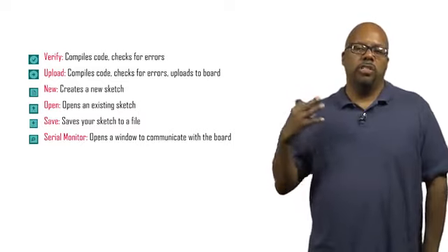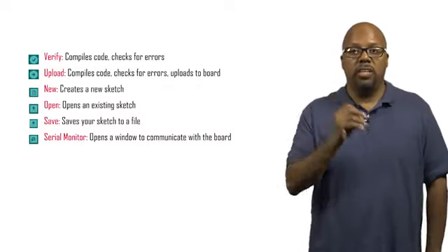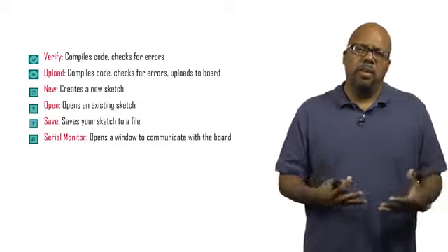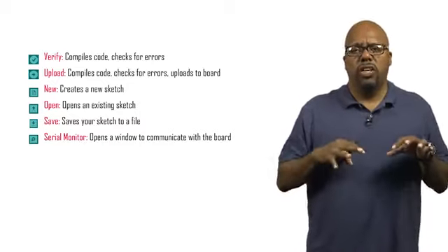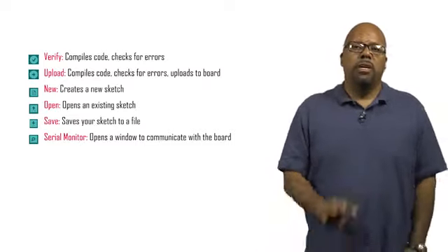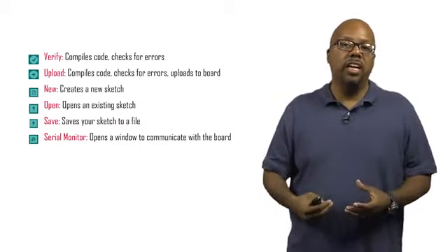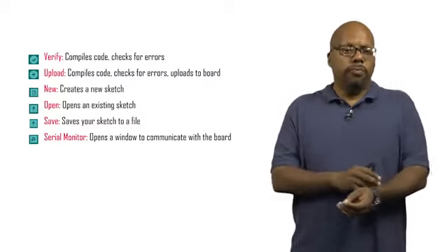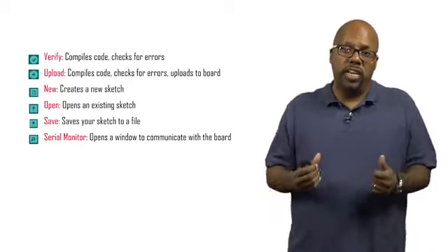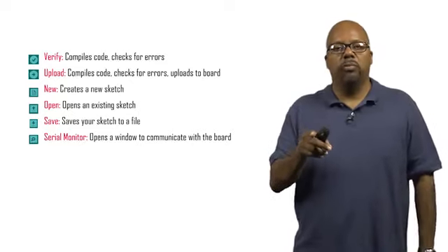But the idea is it opens a separate window. One limitation of Arduinos and embedded processors in general is that they don't have screens. A desktop or laptop has a screen and a keyboard, so it's very easy for you to send data in and read data out. But an embedded device does not. The Arduino doesn't. All it has is a couple of LEDs sitting on it and some pins. So if you want to type data to it or read data from it, like on a screen, you can't do it directly. That's what the serial monitor is for.